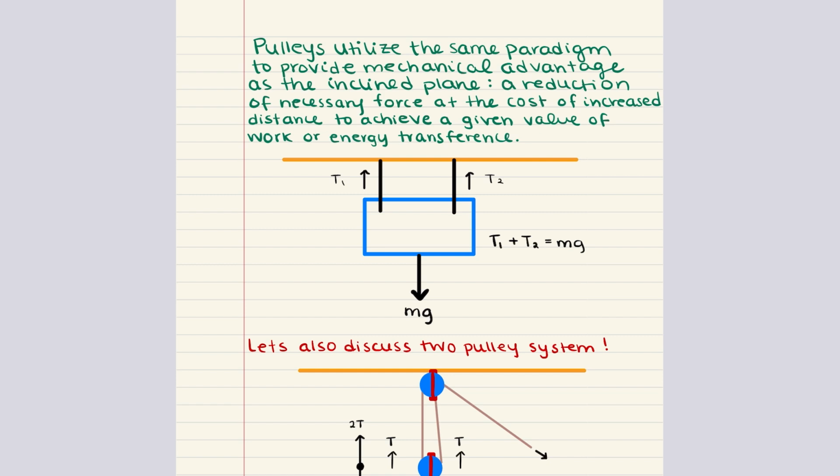something upward. However, it's important to note that this mechanical advantage comes with a trade-off. To gain the advantage of reduced force, you must pull the rope over a greater distance. This is a fundamental principle in mechanical systems. A machine can reduce the force that's needed to accomplish a task, but it usually requires moving a greater distance or applying the force over a longer time.